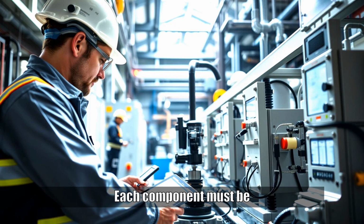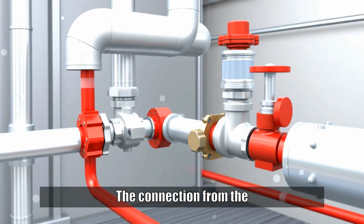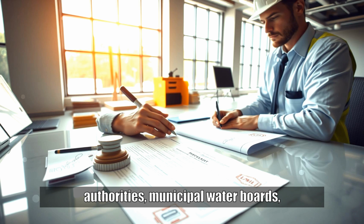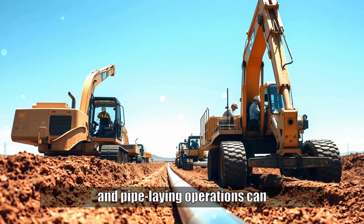Each component must be tested and commissioned according to the manufacturer's recommendations and relevant standards. The connection from the pump discharge to the hydrant network should include backflow preventers, pressure relief valves, and test headers. Before installation begins, permits and approvals must be obtained from local fire authorities, municipal water boards, and building regulators. The design drawings must be reviewed for compliance with codes. Once approved, the trenching and pipe-laying operations can begin.